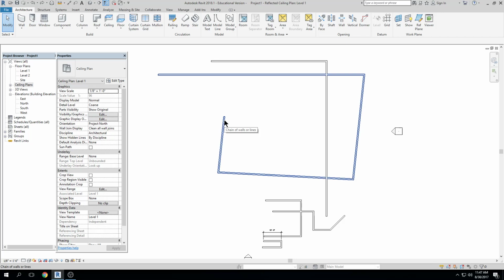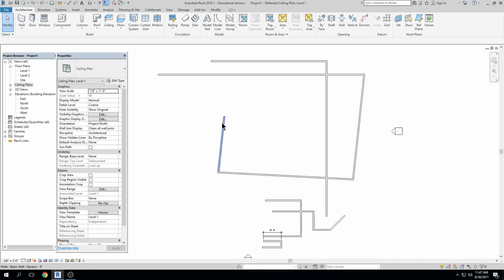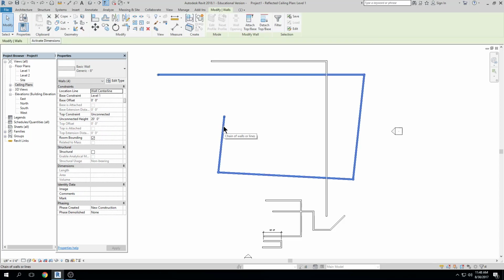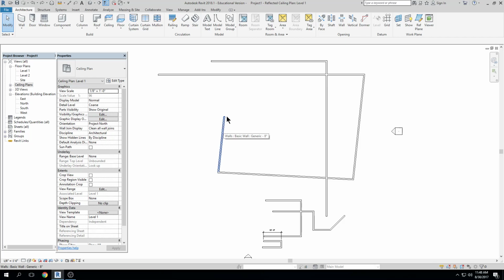Now it's time for me to click, and it selects them. The trick to this is that if I hover, I tab, and then I move, it goes away. But it's pretty helpful. Tab once, click, selected, delete. If I want to undo, Control Z, undo, and it's back. If I tab one time, it selects everything. I can tab again and it goes back to one object. Tab, tab, tab, tab.